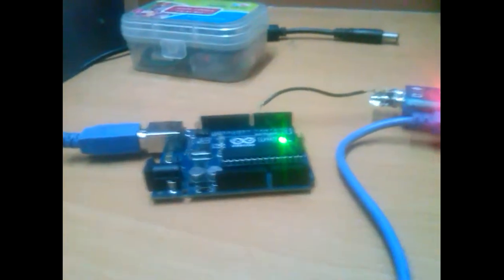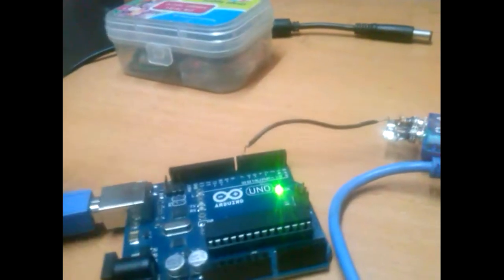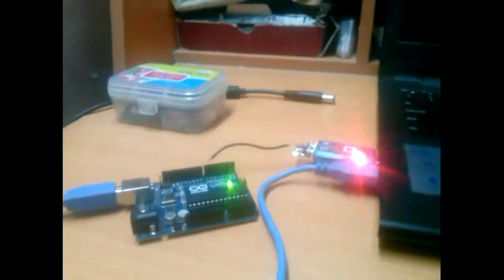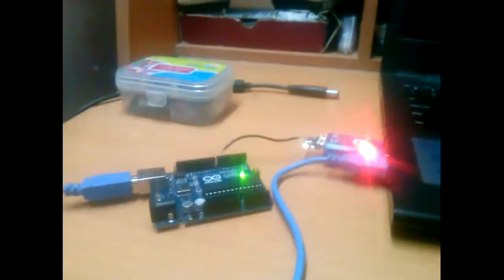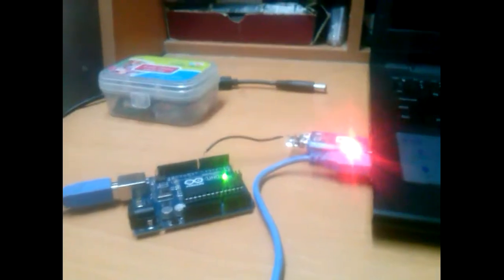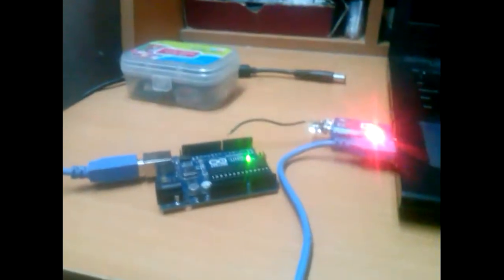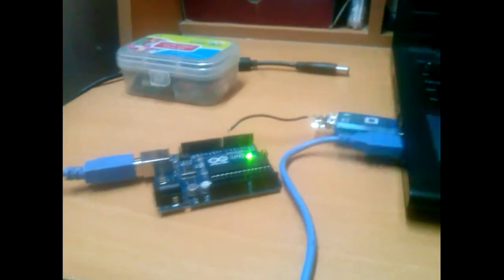In this video, what I'll show you is how to make a tone generator by using an Arduino and a headphone jack. So the setup is like this. I've powered the Arduino using the USB and I've connected the output from pin 7 to the mic of the headphone jack. That's all the setup. For the tone generator we will be giving input from the computer and that would determine the tone that is being played. So this is the experimental setup of this tone generator.